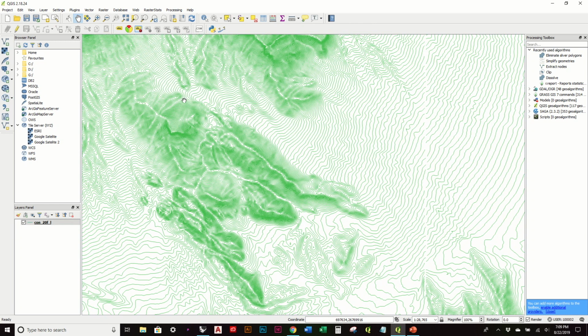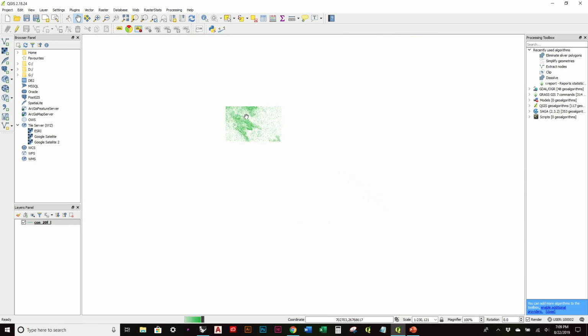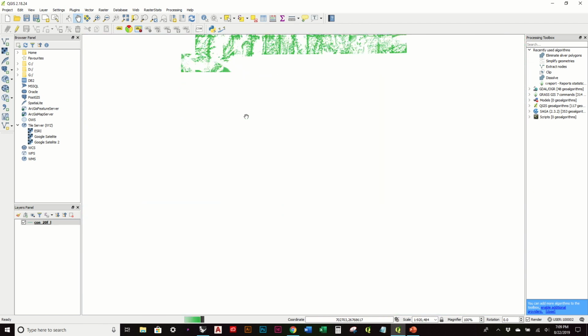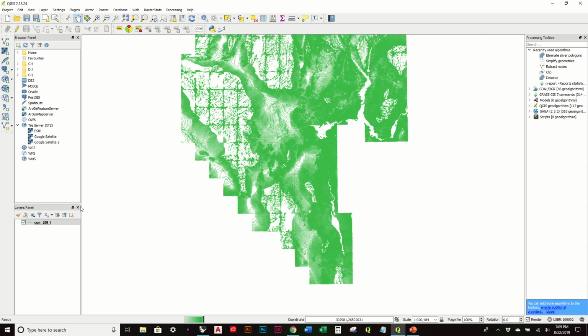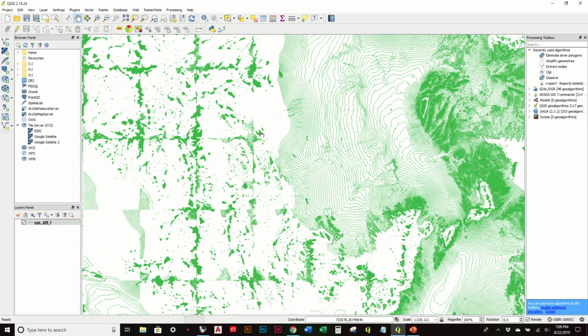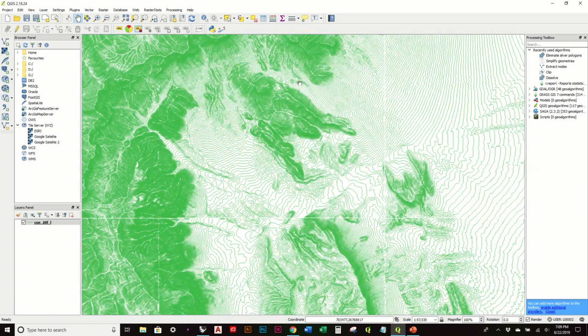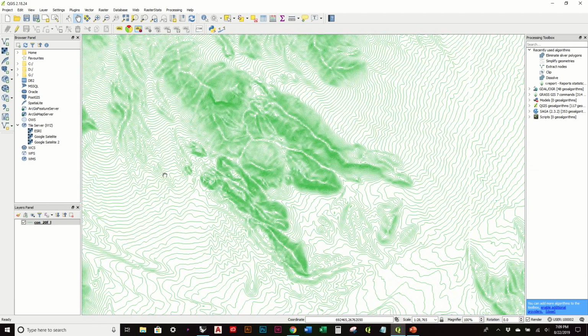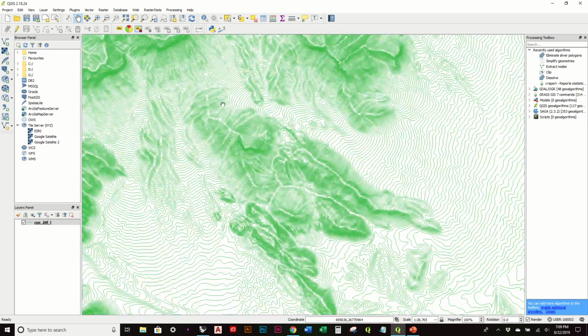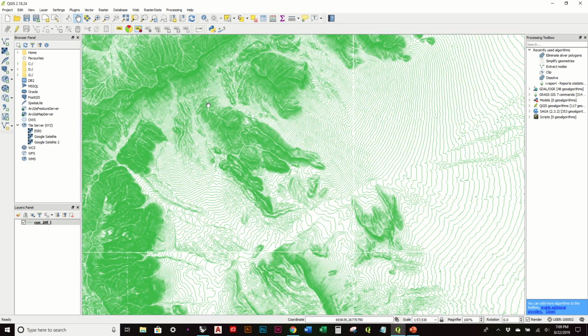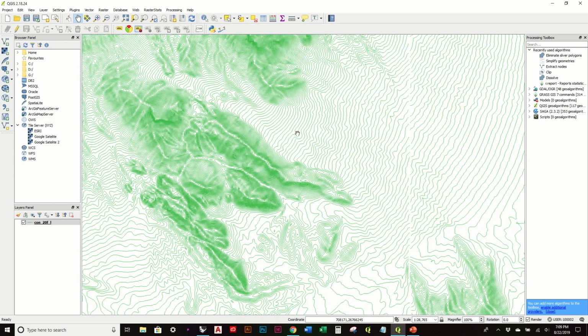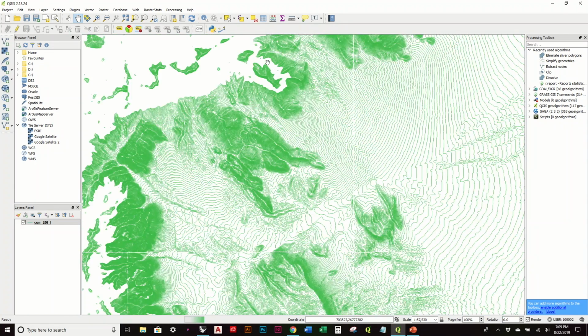And I'm going to use a plugin inside of Grasshopper to help with that as well. So you can see that when I zoom out, this is a pretty big file of just 20-foot contours. If I try to just bring this right into Grasshopper, it's really going to have a fit. So I'm actually going to create a clipped layer that's just going to look at a portion of this. And hopefully what I create a clipping box around will be enough for it to handle.